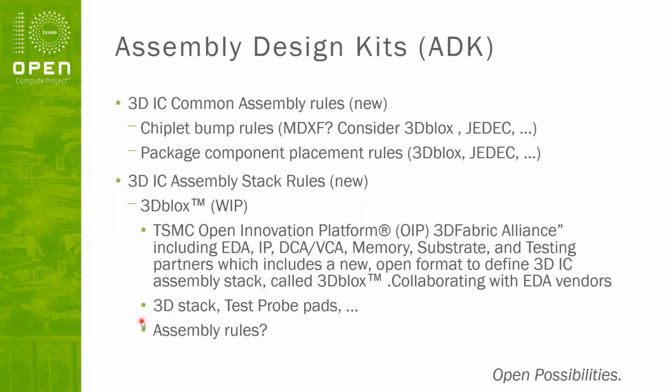Okay, assembly design kits. So this was an idea that was initiated out of a white paper from Intel. They have proposed to have a common set of rules to facilitate interoperability between chiplet vendors. So when they get assembled, each of the chiplets on there would comply to a common set of assembly rules. And they proposed a standard format, and they actually approached each of the EDA vendors and asked them to support this initiative.